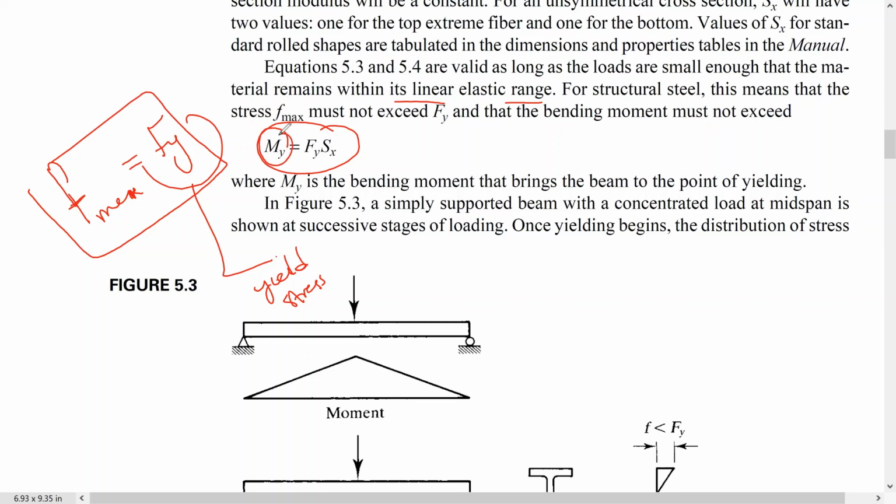Because Fy is equal to My over the elastic section modulus about the x-axis, the bending axis, the maximum moment is M sub Y. This is the yield stress, and this is the yield moment. When I say yield, that means the moment where the section starts to yield.